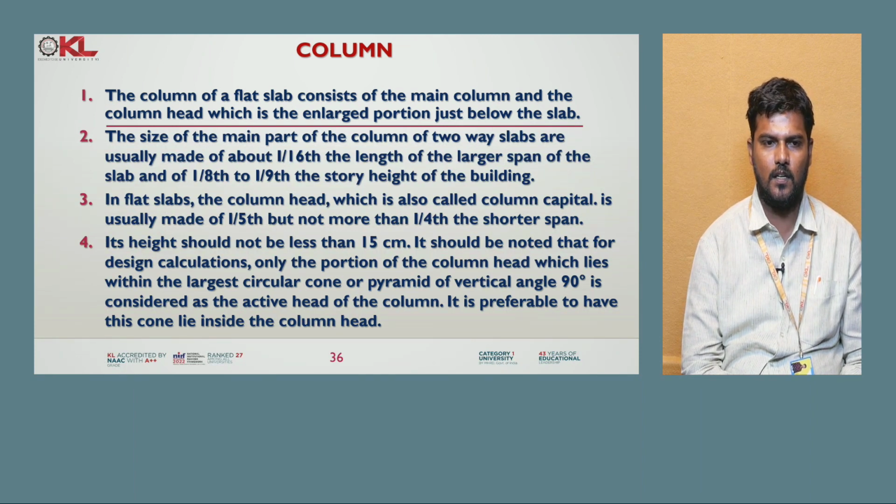It should be noted that for design calculations, only the portion of the column head which lies within the largest circular cone or pyramid of vertical angle 90 degrees is considered as the active head of the column. It is preferable to have the cone lie inside the column head.